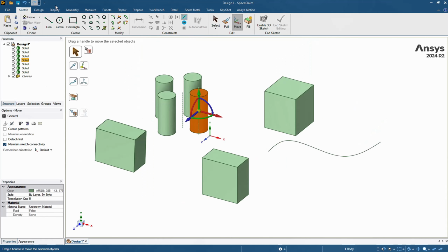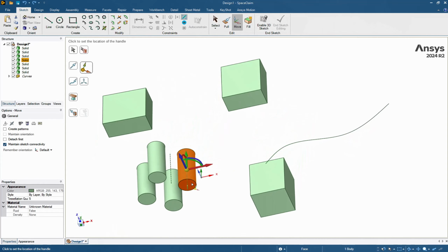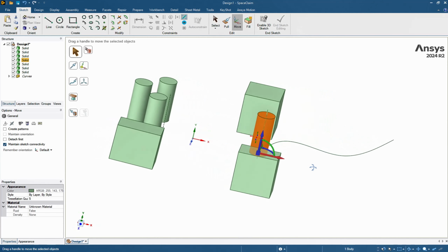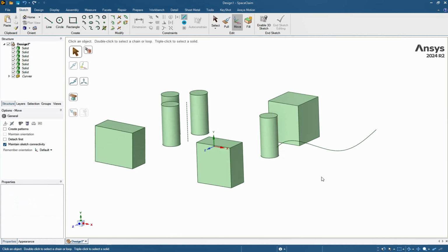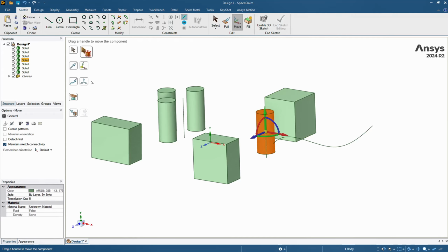However, as you observed, this movement was again unsuccessful because, as mentioned earlier, our reference point was still located at the center of the 3D geometry. To resolve this issue, we use the Anchor command to shift the reference point from the center of the cylinder to its bottom face. Then, by applying the Up to option, we align the bottom of the cylinder precisely with the starting point of the curved path.